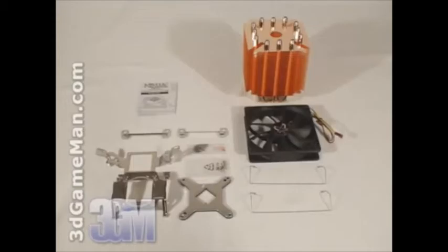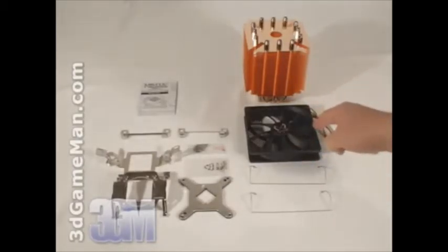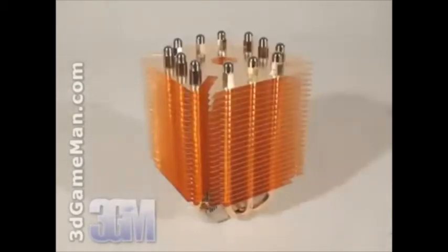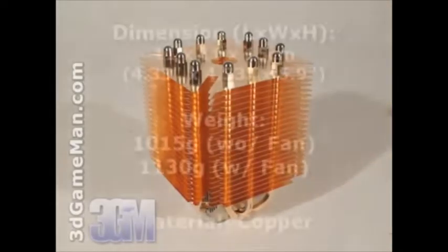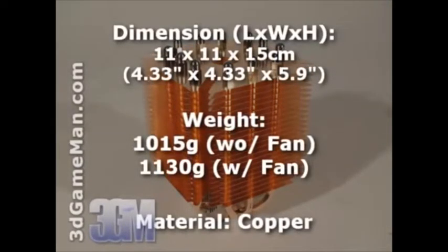The effect of different materials having different conductivities is shown in real-life examples. For instance, CPU cooling systems use copper tubing and aluminum fins to dissipate heat. As shown in our experiment, both of these materials conduct heat very well and are able to effectively dissipate heat.